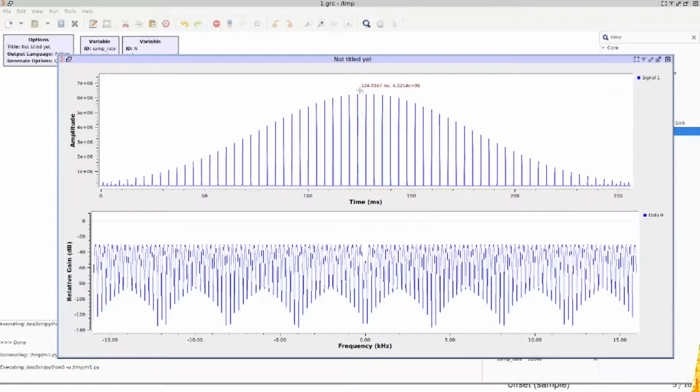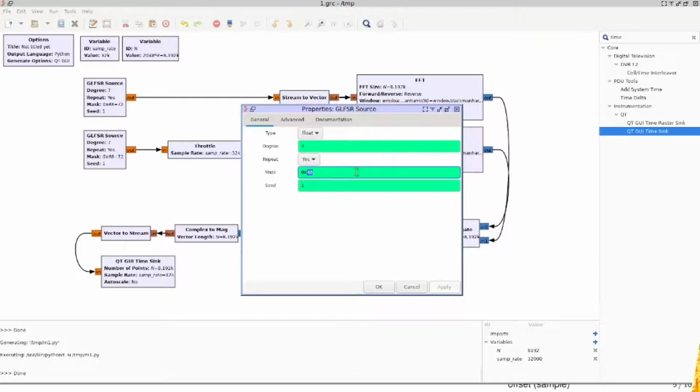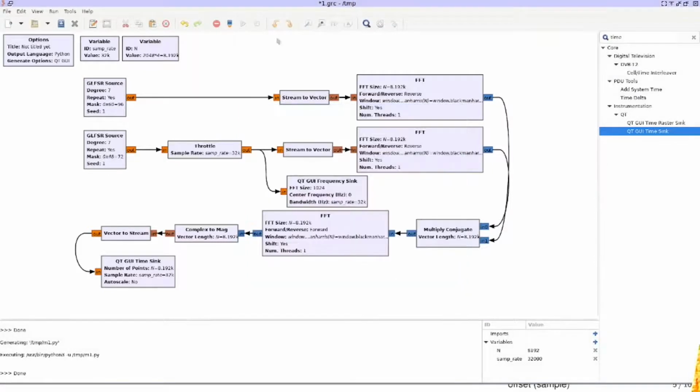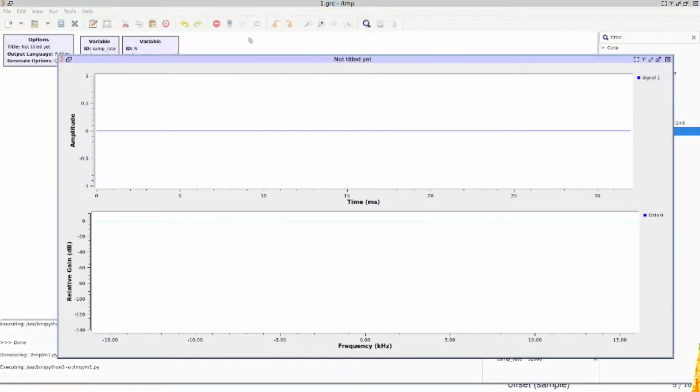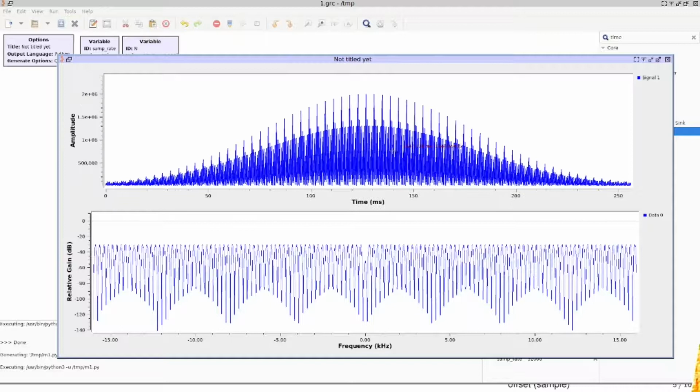So here you have the demonstration that if you transmit a CDMA code, you can identify which is the speaker by selecting the appropriate local copy. If you have a different copy of a pseudorandom sequence, then the energy will not accumulate coherently, and you will not be able to detect the signal from the speaker. Here are the different patterns from the two sides.